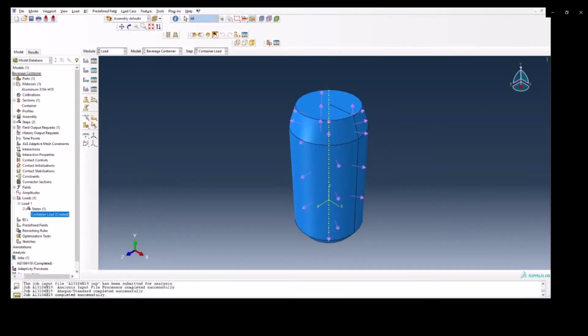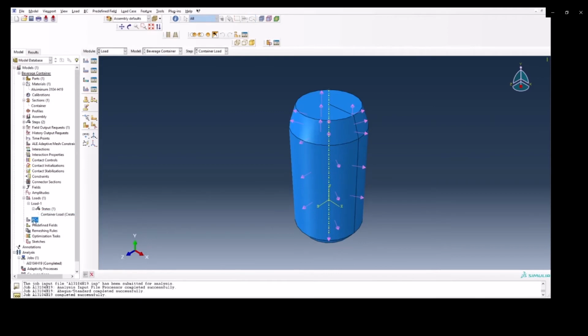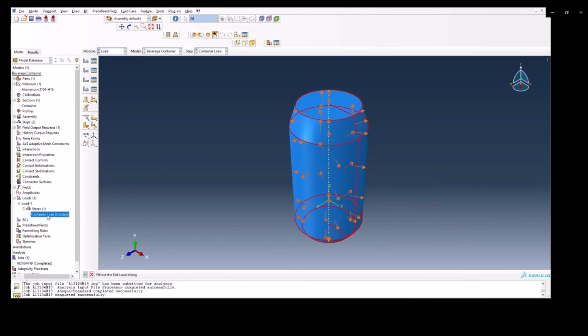Now, for our boundary conditions, we felt that fixing the base of the can would lead to lower stresses than would actually occur because it would be supported by the floor. Now, under this mindset, it became more reasonable not to set boundary conditions, especially since the weight of the can causes forces of negligible scale when compared to the forces we would observe from the internal pressure.